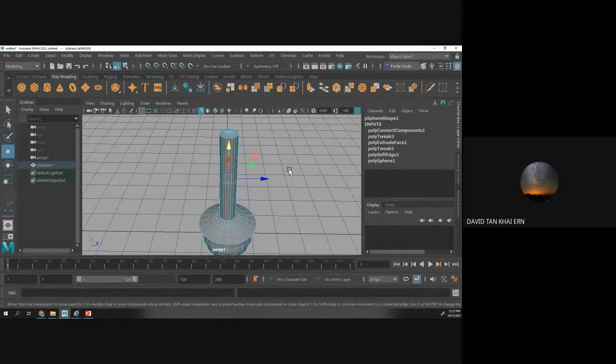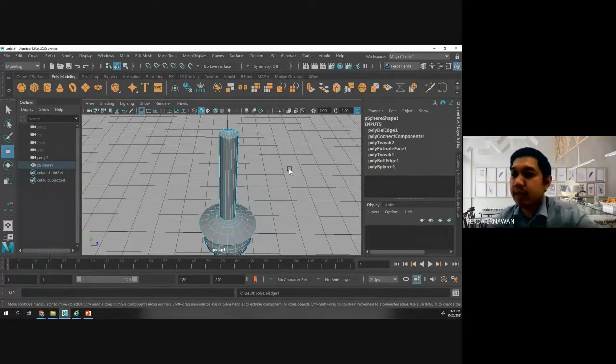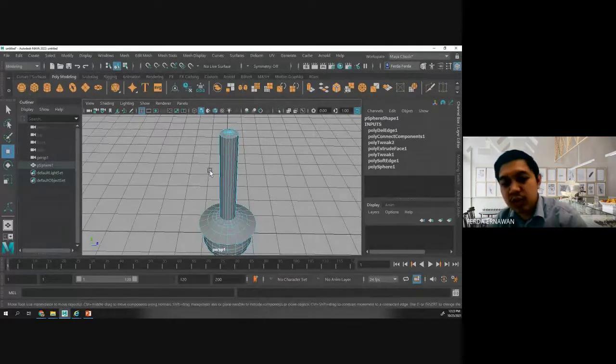Select the point and then press edit and then choose delete. No. What you should do here is press Control and Backspace. Only that way can remove the unnecessary subdivision. You don't try to delete the subdivision.